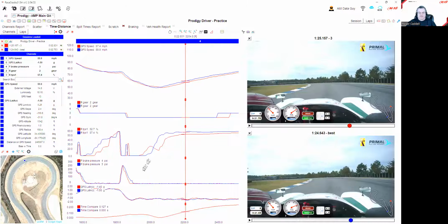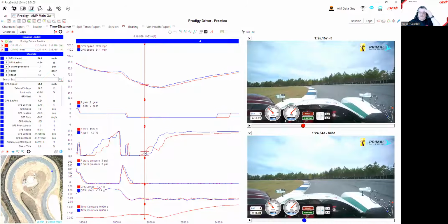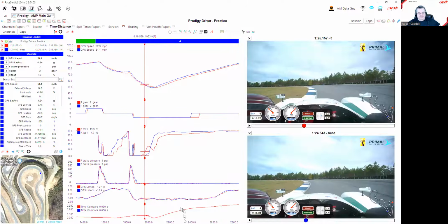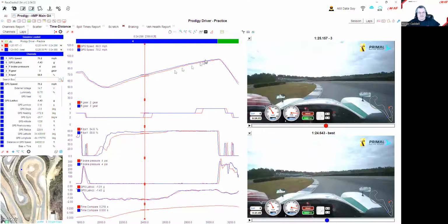That whole thing of getting a little greedy. Race car drivers are paid to get greedy. Don't get me wrong. You absolutely want to get everything you can get. And this driver knew it right off the bat. When you have to do that, you know that you're going to pay a penalty for the rest of this straightaway. Your job is to get it up there where you have gotten back to full throttle as fast as you can and as early as you can, but without the release, because that, again, upsets the platform, probably starts an understeer, and the rest of that exit of that corner. And then, of course, the payoff process, which is the rest of that straightaway, has to be paid for because of that little error of getting on it a little bit too soon.